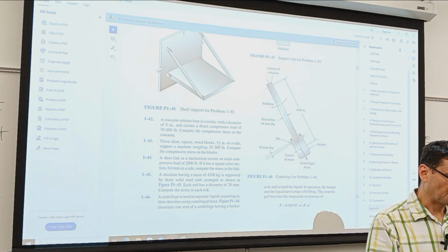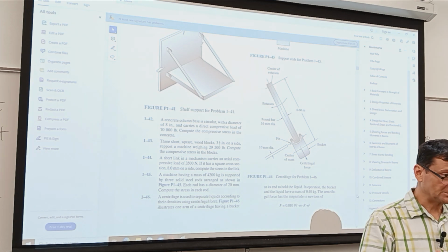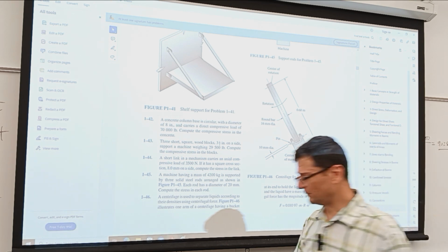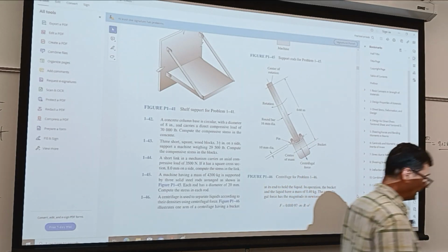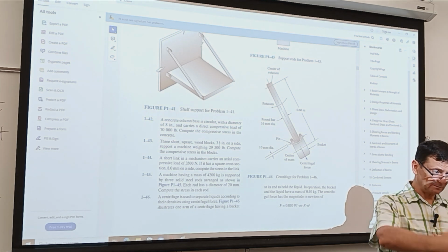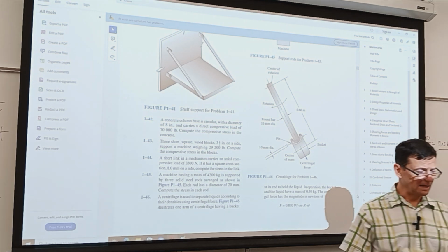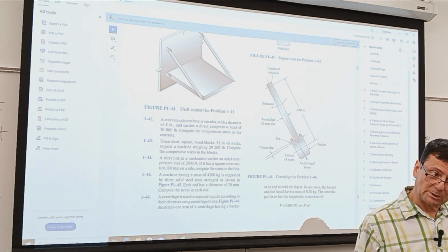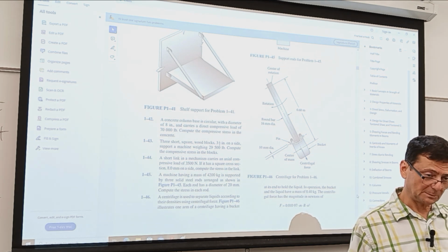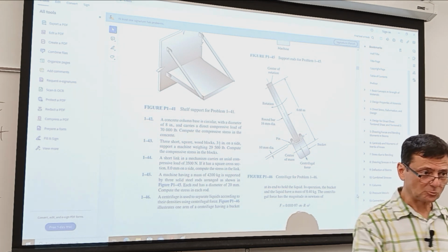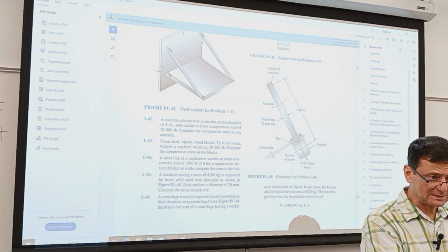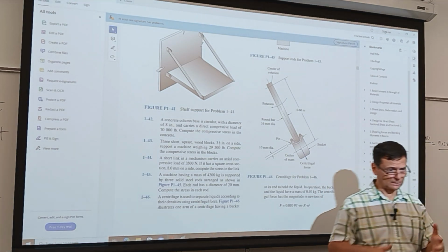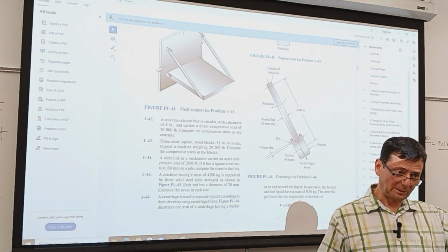They do primarily thick plates and rolled steel for automotive, and they form it in structural shapes. But they do testing. They cut specimens, they have tensile machines, and they attach bulletins to the batch. If the batch does not match the requirement for one customer, they go with the next one. They use recycled steel as a primer. They do some sorting, of course, but based on how well they recycle and how that batch worked, it may or may not be within the acceptable limits for one customer.